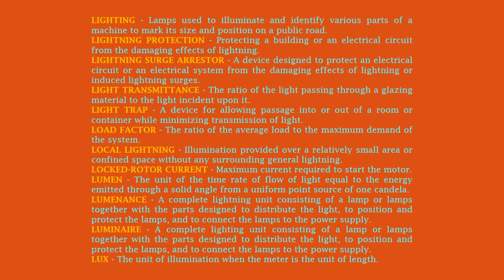Load factor, the ratio of the average load to the maximum demand of the system. Local lighting, illumination provided over a relatively small area or confined space without any surrounding general lighting. Locked rotor current, maximum current required to start the motor. Lumen, the unit of the time rate of flow of light equal to the energy emitted through a solid angle from a uniform point source of 1 candela.